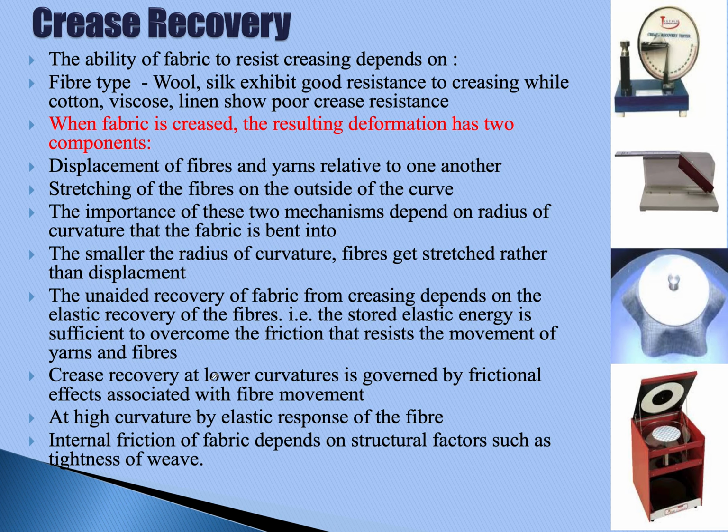Crease recovery at lower curvatures is governed by frictional effects associated with fiber movements. However, at higher curvature, it is governed by the elastic response or the stored elastic energy in the fibers. Internal friction of the fabric depends on structural factors such as the tightness of the weave. So this is a constructional parameter which affects the internal friction.